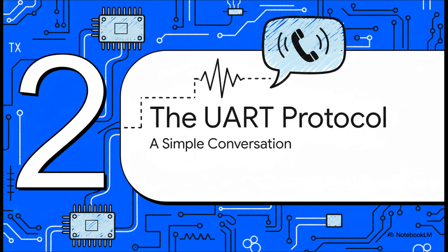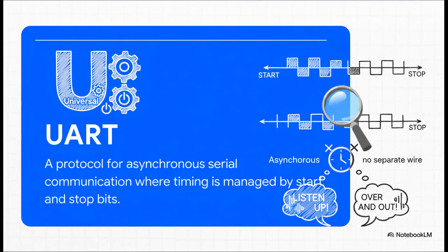This is probably the one you'll run into first. It's called UART. And if serial communication is the general idea of talking, you can think of UART as a specific dialect. It's like a direct, one-on-one phone call between two devices. Super straightforward. UART stands for Universal Asynchronous Receiver Transmitter. Universal because tons of things use it, but the real key word there is asynchronous. What that means is there's no separate wire sending out a beat, a clock signal, to keep both devices perfectly in sync.